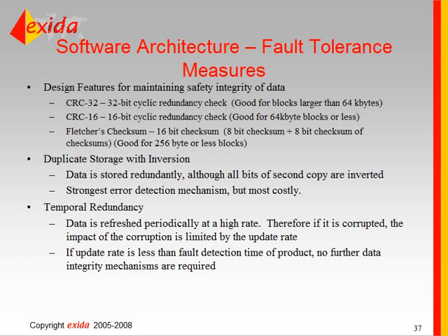And then we also need to concern ourselves at this time with the safety integrity of data. And so if the data gets corrupted, how can you make sure that that's detected? You can use a CRC, which is a cyclic redundancy check. There's also something called a Fletcher checksum, which is a little bit easier to implement, but is only useful for smaller size blocks. So a CRC, you'd calculate that on a block of data. That block of data changes, the CRC changes, and so therefore if that block of data gets corrupted, you'll find the CRC has changed and you can detect the corruption.